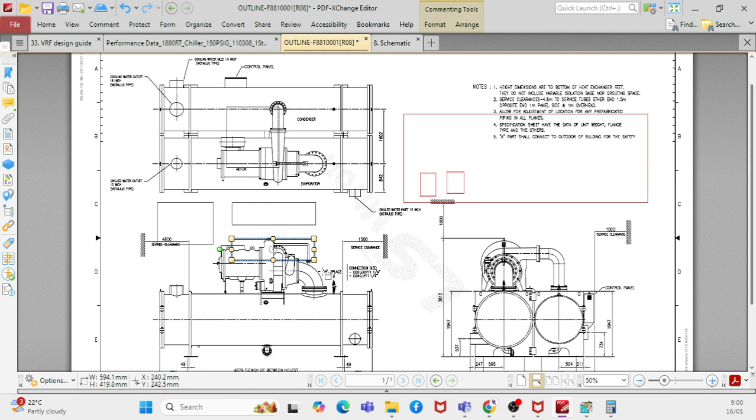When you consider, for example, here there is no ambient temperature to consider, and there is no need of elevation. But elevation matters when you do the cooling tower, and here there is a space constraint. So for water cooled chillers, you don't have to consider the elevation, because it's water, not air cooled. Okay, yeah. That's why I'm asking.